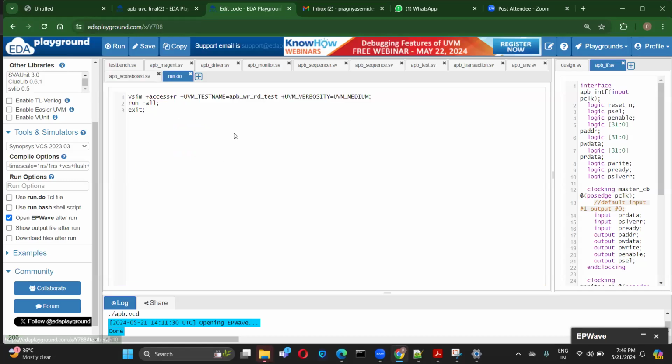And this is the run.do script. You just copy and paste it into your environment, because using this only we run our particular code. This is the run.do script file where we run the particular test case. As we always discuss, I have told you so many times, we provide the test case through the command line argument. Otherwise, it will take whatever is in the run test. This is what I was talking about. And I was also saying, instead of dollar display, use UVM info.